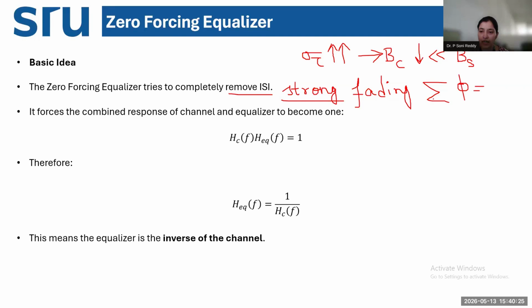The result is a fast fluctuation in the amplitude of the signal with respect to time. This happens when the phase variation is almost equal to pi or 180 degrees, and then we experience destructive interference. So the signal amplitude becomes strongly affected, and we lose some part of the signal when it is transmitted through the wireless propagation channel.